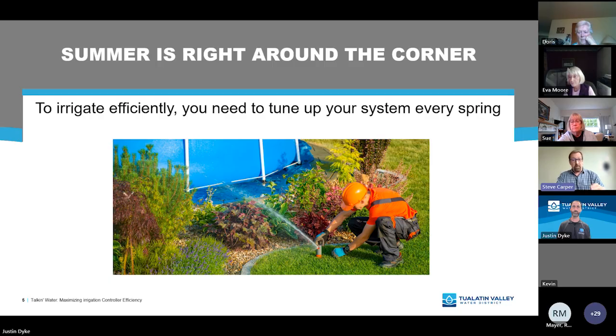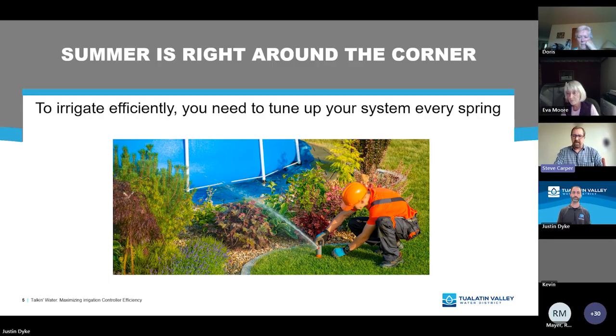The other thing that you can do, if you really want to get into it and you're confident something seems amiss, is go around and count the individual sprinkler heads. If you know the manufacturer, you can determine, based on the pattern, say a full circle, half circle, or quarter circle, you can go on the manufacturer's website and pull up a nozzle chart, and determine the flow rate, gallons per minute, of that type of sprinkler nozzle. So, for example, if you've got 4 quarter circles that are rated 1 gallon per minute, you know that zone should be using 4 gallons per minute, right?